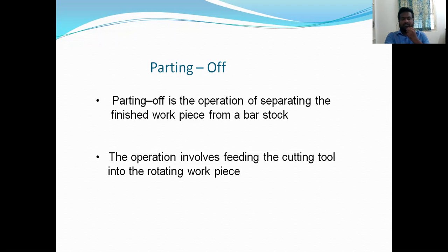The operation involves feeding the cutting tool into the rotating workpiece. By doing this operation, parts are separated from one another. Okay, the name itself tells: parting off. It is the operation of separating the finished workpiece from a bar stock, where we give feed to the cutting tool into the rotating workpiece.